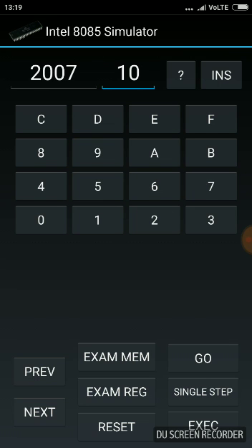Note that when we use the decrement instruction, the hexadecimal number gets decremented by 1. So after 10, it goes to 0F, right? And after 16 steps, all the way it goes to 00, and after that our loop comes to an end. Right, next I set up a loop.